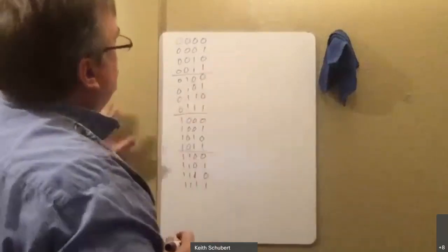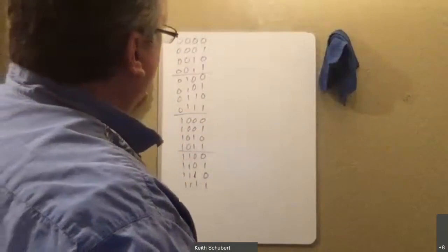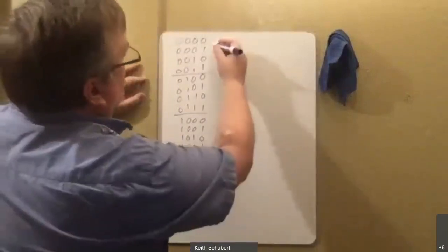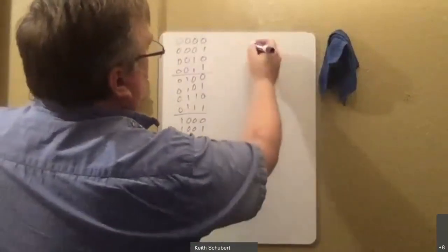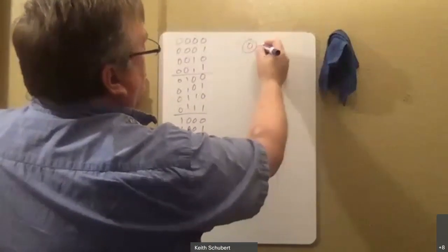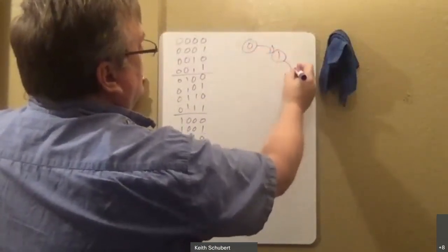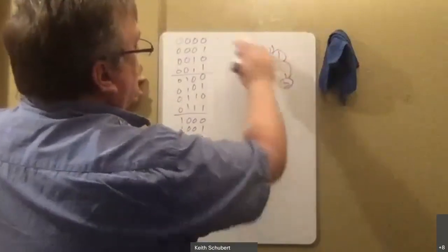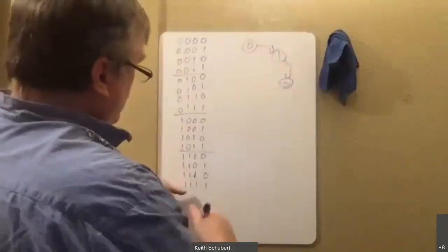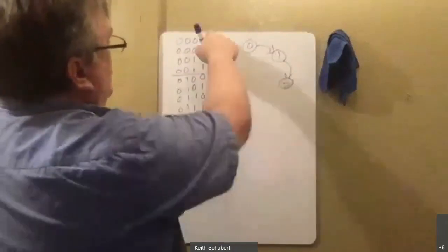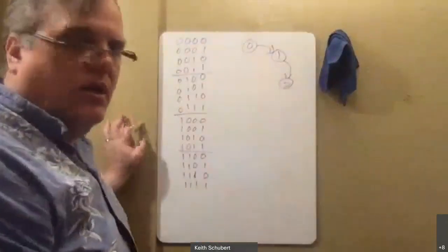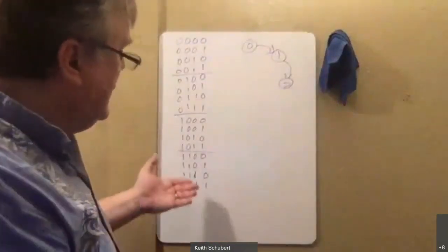Okay, so this is my sequence inside of here. And again, if you want to think of this, this is 0, 1, 2, 3. We kind of draw it in a picture as 0 goes to 1, goes to 2, so on and so forth. This is just a ring going around. For the last one, 15 comes back up to 0. So this is a mod 16 counter.